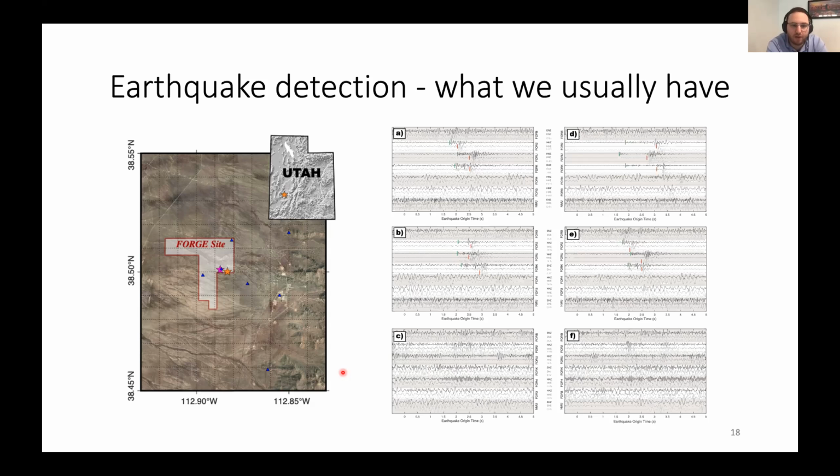So we try to squeeze everything we can from the fact that we have this spatial continuity and this array processing approach, but in the very basic form of the measurement, geophones can listen to quieter stuff. And to me, that's the difference. Of course, that has to do with the exact fiber you use, the coupling, the casing, and all the installation details that are very important. But I still think at this point, and this DAS data was with an engineered fiber, by the way, on a point-by-point comparison, geophones still do a lot better. And I think that's the reason for this difference.